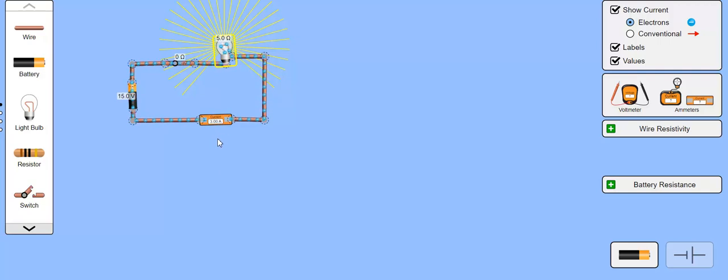So you already know these principles. The principle of pressure, flow and resistance works the same in all circuits, whether it's fluid or air. Any circuit works the same. You already know that if you increase the pressure in a fluid circuit, the flow of liquid around that circuit will increase proportionally to that.